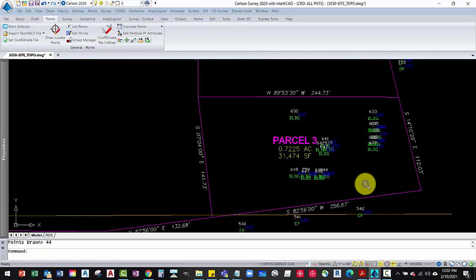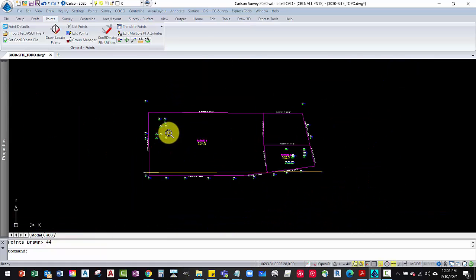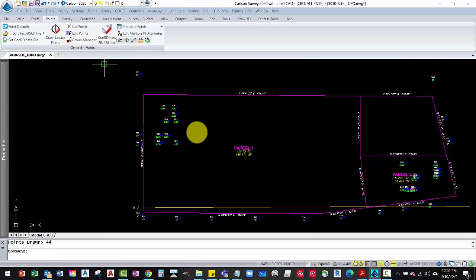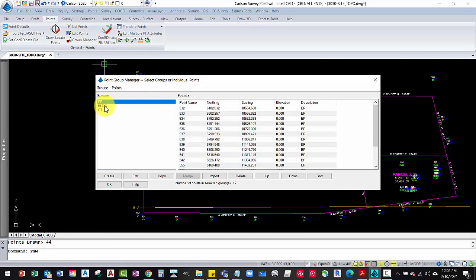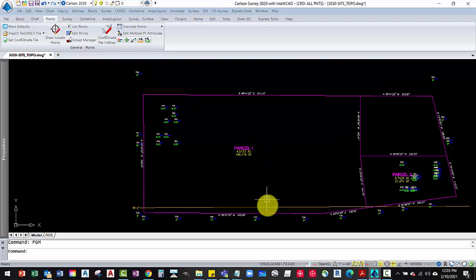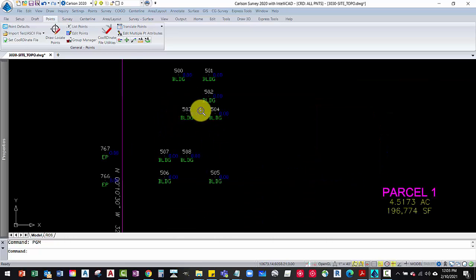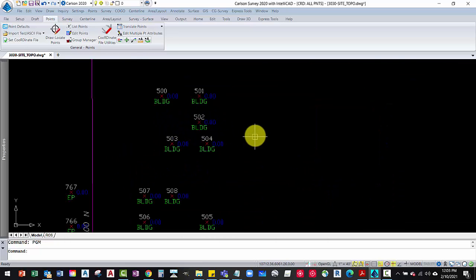It looks like it picked up my EPs as well. Not sure why it did that. I'm going to go look at that for a second. It shouldn't have done that. Oh, it's because I clicked on EP. All right. Well, that wasn't too smart. So building, and then I clicked EP as well, so that's why it drew both. That's fine, it works. They're in different places. You can see the EP, edge of pavement, is out around the outside anyway, and the buildings are on the inside. So that actually works to have both those up there.